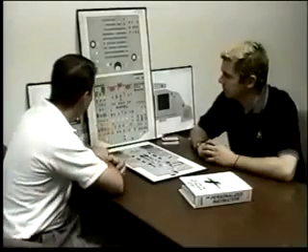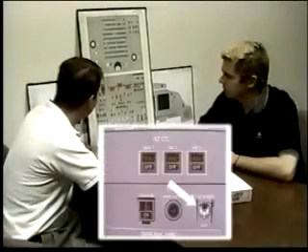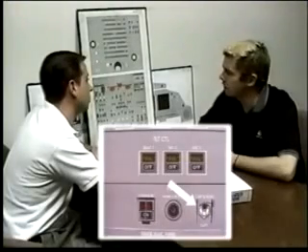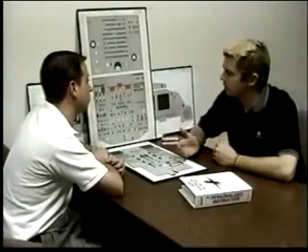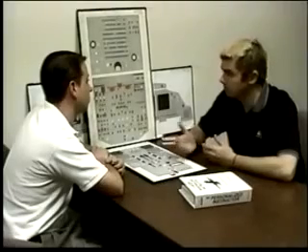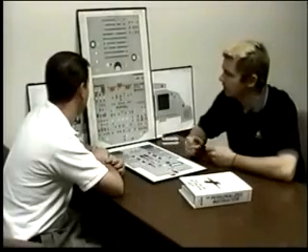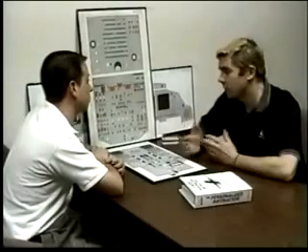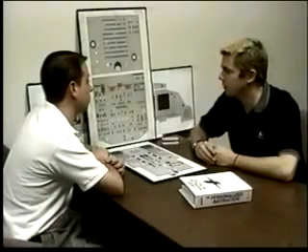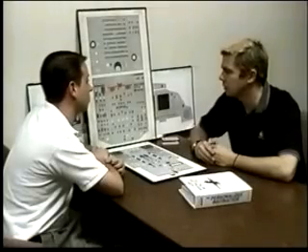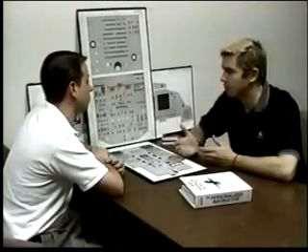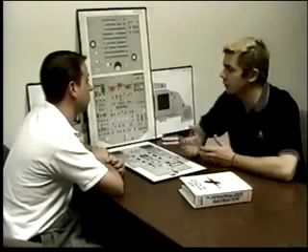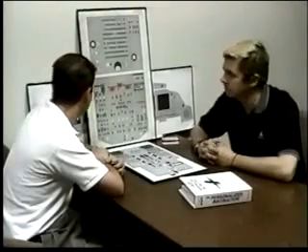Then you have a switch that's safety wired, says captain and purser. When it's in the captain purser position, which it's safety wired to at United, the captain and the flight attendant, either of them can start the evacuation. Theoretically, when it was selected to captain only, it was basically wiring out the flight attendant from being able to initiate the evacuation. Although it's wired to captain purser at United Airlines, for the last 3 years, maintenance has deactivated the switch, so we couldn't even select it to captain if we wanted to.